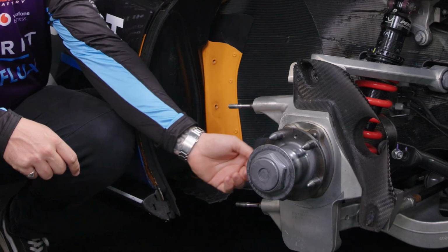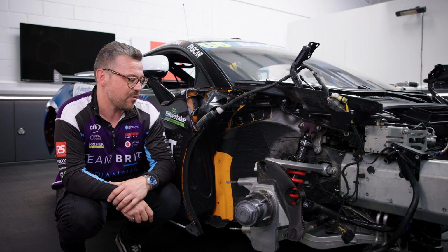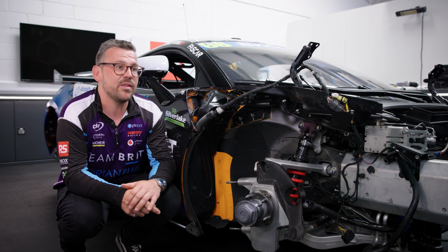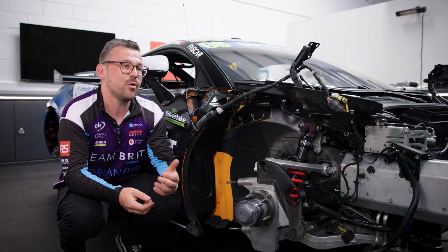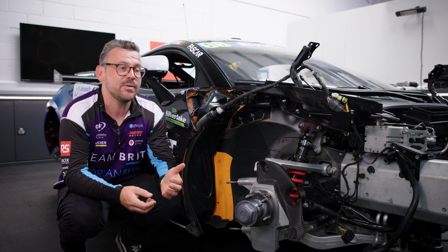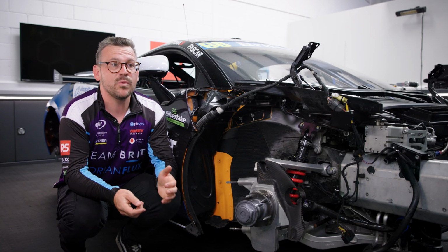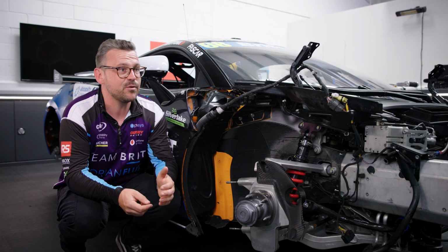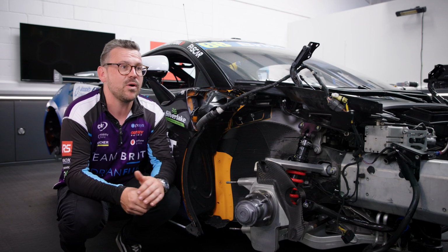And we do that here with a wheel speed sensor that's connected to the upright in this corner. This measures the wheel speed of the front right. It allows us really to see how fast that wheel's going, and it tells us a lot of things about the car. Not only can it tell us things about what the car's doing, but it also tells the onboard dynamic systems things to do and things that are going on with the car. Specifically, it can tell the car when the front wheels are locking up and ABS needs to activate. Without these wheel speed sensors, it's very difficult to drive a race car, and it's very difficult for the engineers to understand what it's doing and why it's doing it.